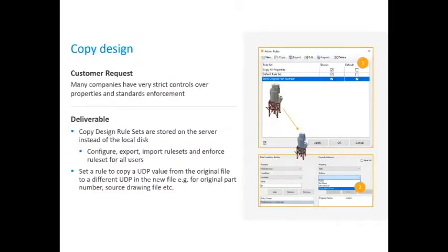All right, another advantage here, copy design has been a great tool within Vault for a long time. Hopefully if you are using Vault, you're taking advantage of that. I know some of our customers still try to use the save a copy within Inventor, and it can work fine for certain things, but man, the copy design is so much easier to use, and you can actually do multiple assemblies if you're working in Vault Pro. So that's kind of an advantage.